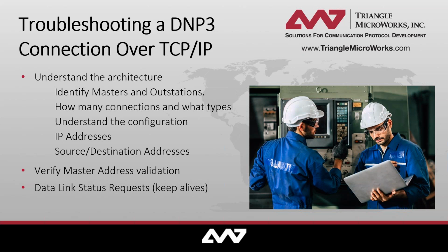Once all of this has been checked out and your devices are connected, you should see data link status requests. These are a form of keep alive messages to verify that your devices are remaining connected. While TCP/IP does have a built-in keep alive message, the rate at which it's checked is far too slow for some DNP3 connections.